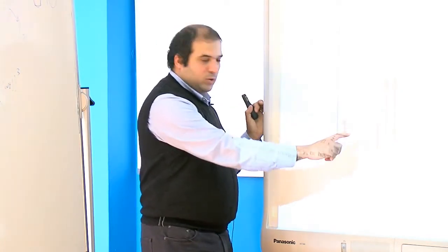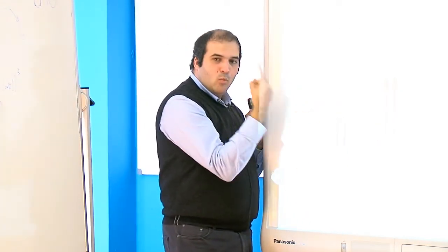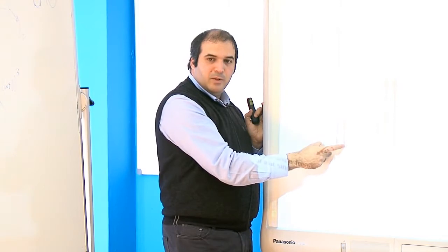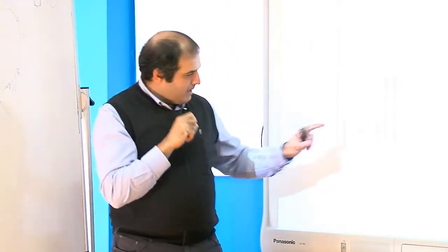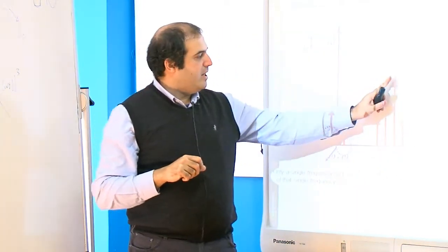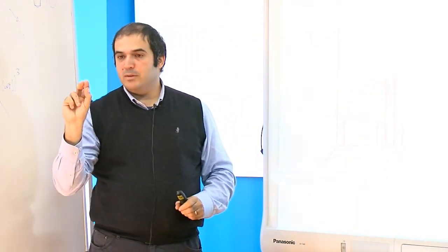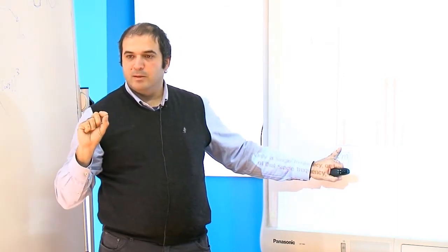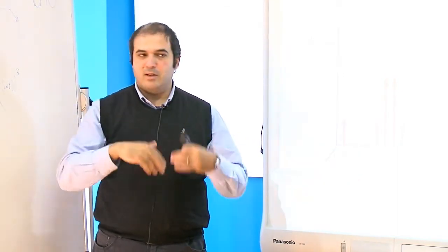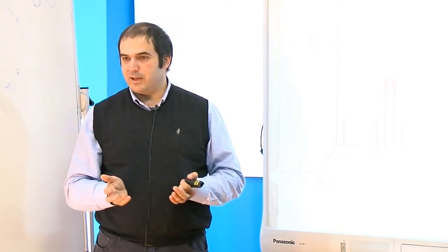And when I'm doing this, I'm only exciting one frequency of the video bandwidth, okay? And this is important to see. In one tone, if they are separated by 200 kilohertz, as I said, this signal will appear at 200 kilohertz. And this is important because it can change completely the behavior of your device.